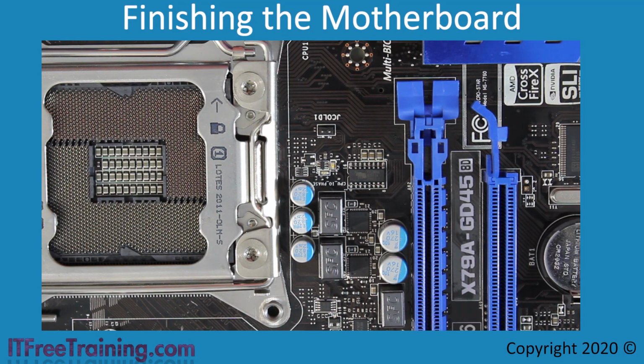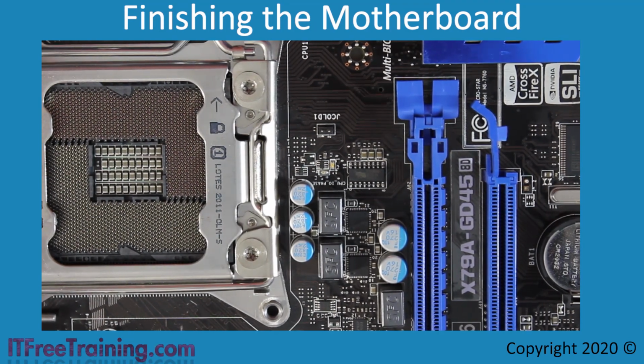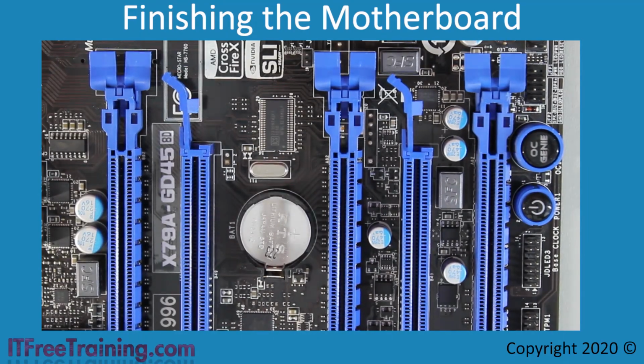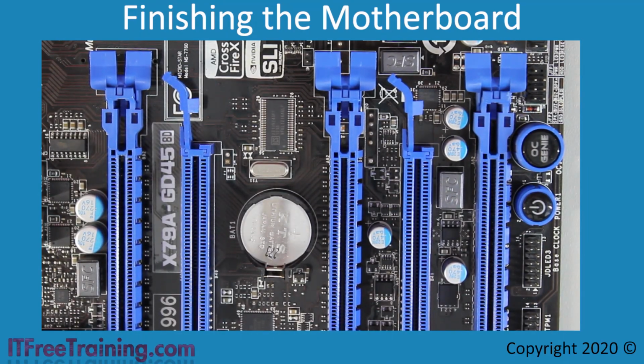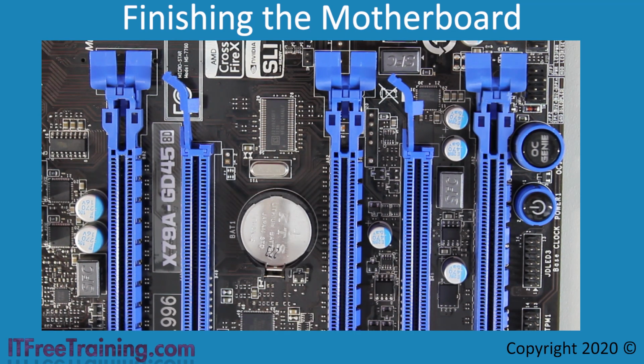If you have a close look at the motherboard, you can see the traces that lead away from the CPU. Without counting them, it is pretty clear there are nowhere near 2011 traces leading away from the CPU. This is the first clue that there are multiple layers used in this motherboard. The next clue is, if you look at the PCI Express slot, each x16 slot has 82 pins. But it is pretty clear there are nowhere near that many traces heading in that direction. Also, you can see the large number of components taking up space on the motherboard. This makes it difficult to run traces around the motherboard simply because the components are in the way.